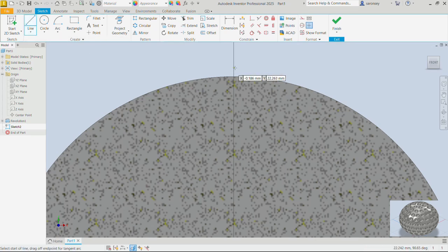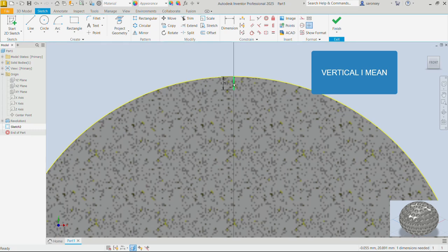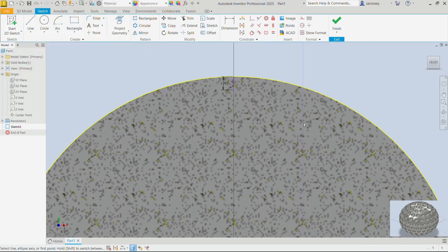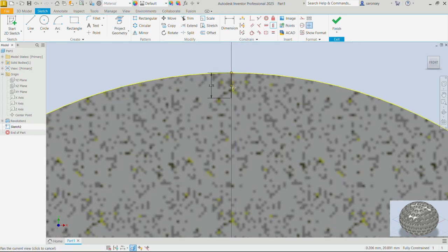Let's pick the line command first. We want to draw a line from this point here downwards. Let's do a distance of 1.25 and enter that. Let's right click and OK first, and make sure that this line we've drawn here is horizontal. So we'll select that line and choose the horizontal constraint command up here. That line is vertical already. Okay, so we will cancel that and make horizontal the midpoint of that line rather, and this top point here, that will constrain the line.